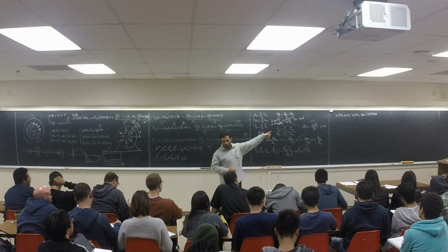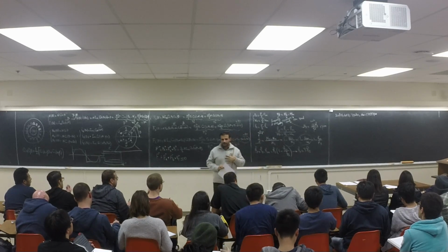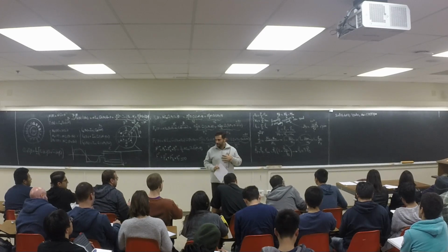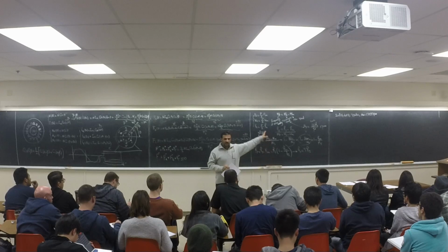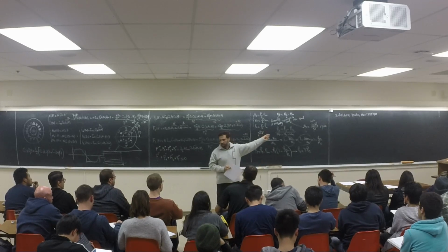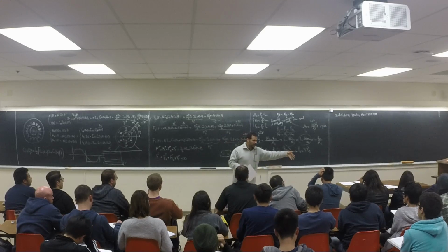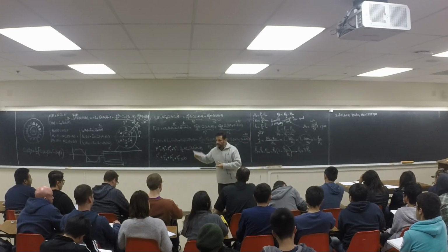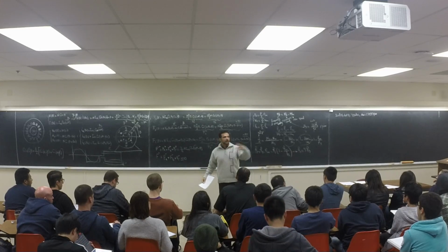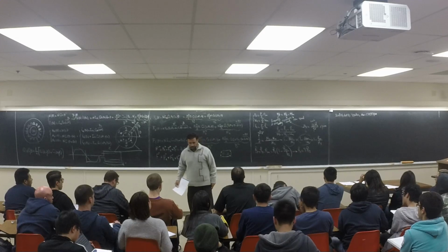It has 4 poles, and the rated speed of the machine is 1755 RPM. What does it mean? When you put the rated load, I don't know, 10 kilo, whatever it is, it didn't tell us how much it is. But when you put the rated load on the machine and plug it into the 208 volt, 60 hertz supply, the machine is going to rotate at 1755. That will be the speed of the machine.